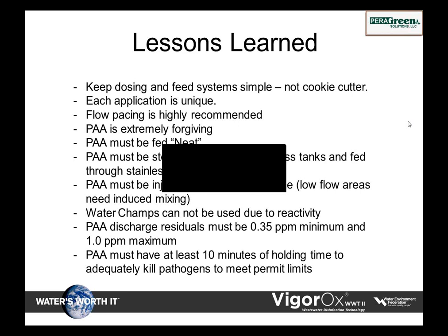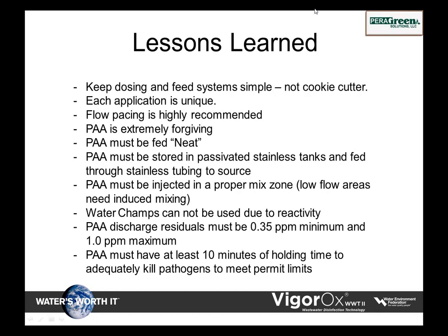All right, we had to make sure we had the combined discharges from the 3 clarifiers. We're lucky there's one pipe that goes down, makes a 90-degree turn, and goes directly to the old chlorine contact chamber. It's a typical 30-minute design, concrete basin with overflow weirs. They've installed a couple of extra weirs for mixing. They have stainless on overflows, so they've put some modifications in there. But again, very simple design system.